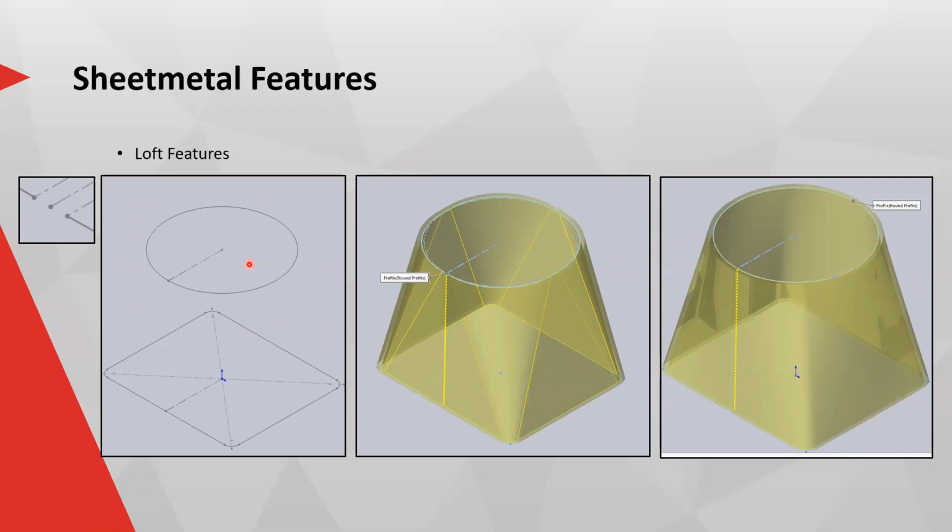So what I want to mention to you is there's two main types of lofts within the loft feature. There is a bend loft, which is like the one I'm hovering over now. It will actually give you the flat pattern, and it does give you all the bending instructions on the flat pattern. The form feature does exactly the same. However, it retains the formed look. So it doesn't look like it's been bent, but rather formed over a mold, for example. And it does still give us bend instructions. However, it does come with a warning where it says it's not that accurate.